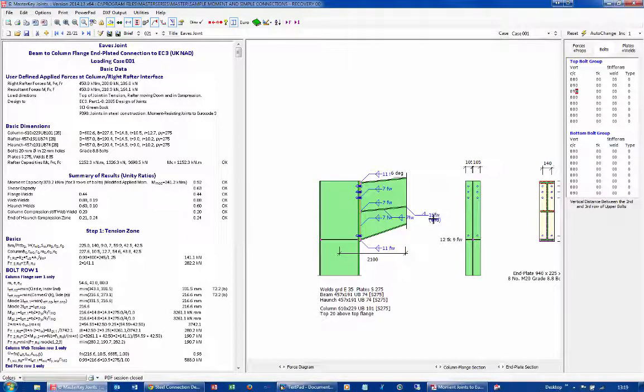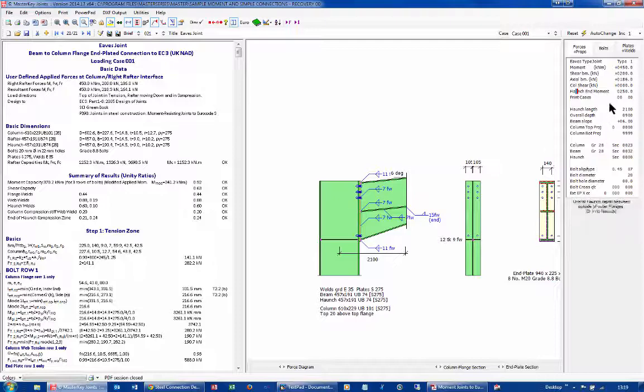And one of the ways to reduce that is to put in the end of haunch moment, and that will help reduce that weld. This is just the default, which is 0.7 of the thickness, or full depth actually in the end of that. And these are a bit high, so I'm going to come back and rationalize my welds.